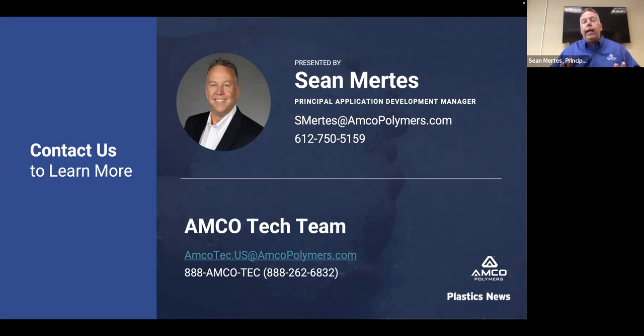The second thing that I had a couple of customers do is put a nozzle shutoff on, so that as they're plasticating or recovering, they can actually have the mold open and be opening the mold during plastification. So that's one that's really unique, and I really like that application.